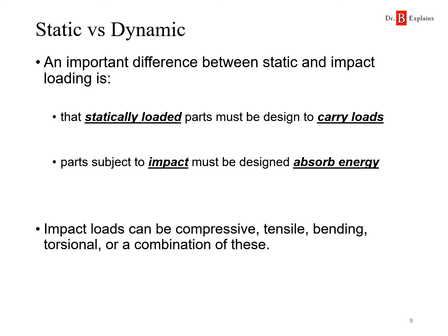But first, a very important difference between static and impact loading, and that is whenever we're designing parts or machine components to handle static loads, really we're designing to carry loads or stresses. But when we're designing parts that are going to be subject to impact, then this must be designed to absorb the energy. Now remember this mechanical analog, the mass is going to have some potential plus maybe some kinetic energy, and the spring, which is the component that's receiving all that energy, more than carrying a stress, has to be able to absorb that energy without failure.